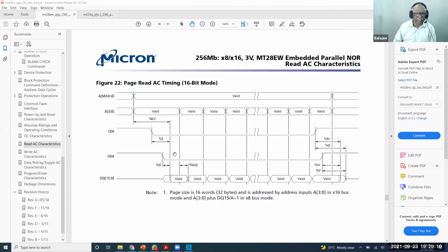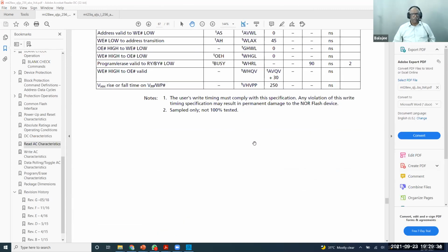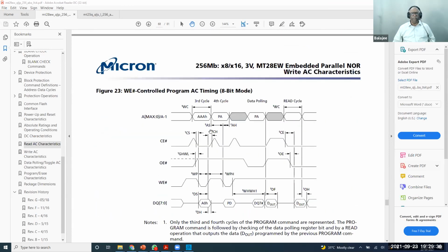See that? There's nothing more. I told you, see here. It will go like this. Data. Then address will go like this. Then the signal will go like this, high to low or low to high. There's nothing more than that. And they will tell you the timing between each two. This is what a timing diagram is. Any timing diagram, they will tell you this. They write it and then give a timing. See this, when this time there is no data, that's why they black it out.